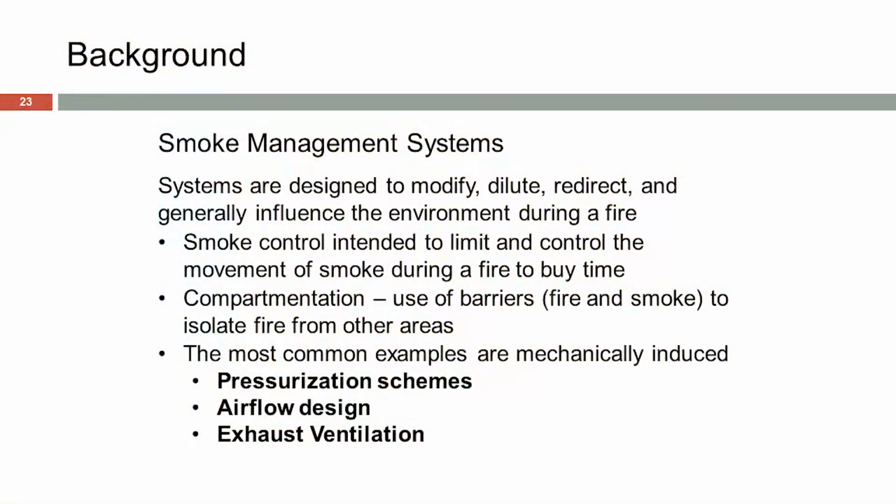Stack effect. Stack effect is an interesting phenomenon that bears its own discussion. It's not going to happen today, but stack effect is an important factor to consider. Those differences in air pressure from inside to outside of a building structure based solely on the temperature differential from inside to outside, knowing that if you're in certain climate areas, it absolutely reverses summer to winter. In other areas, it's not so dramatic. But it can be a very large factor in the design concepts. Always factored in stairwell construction, because if you're doing a 10 to 30 story building stairwell system, you're going to have stack effect in that amount of vertical rise in a building.